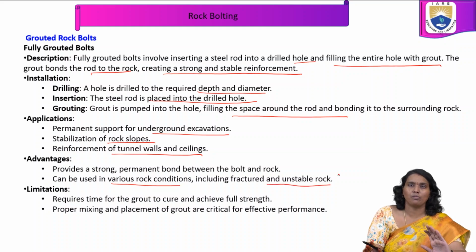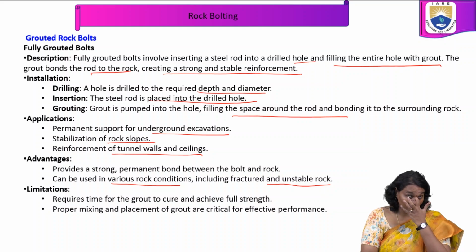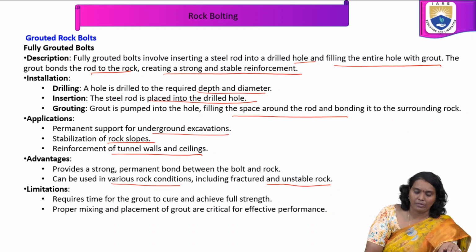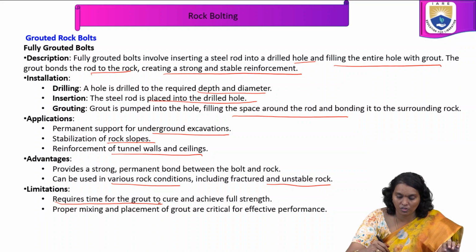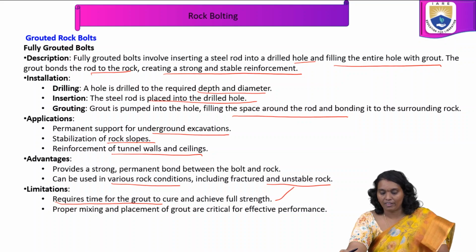For fractured and unstable rocks, we may consider fully grouted bolts in that scenario also. There are some limitations: it requires time for the grout to cure and achieve full strength. Proper mixing and placement of grout are crucial for effective performance.